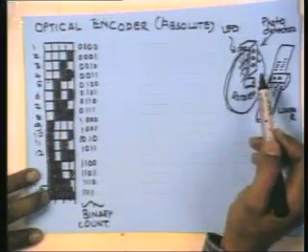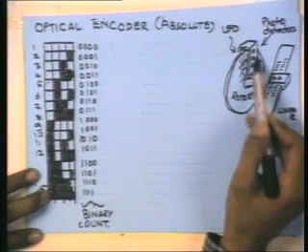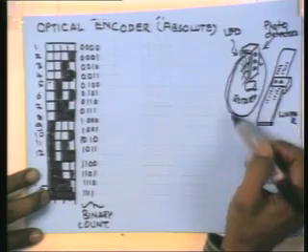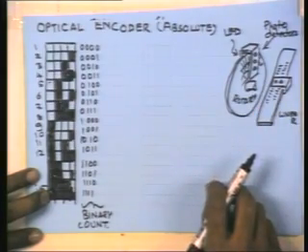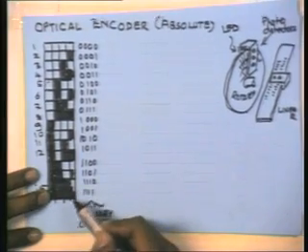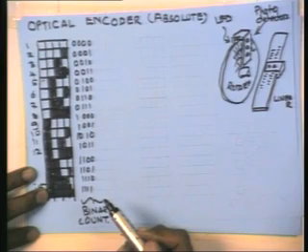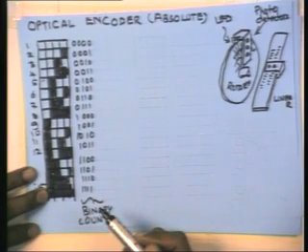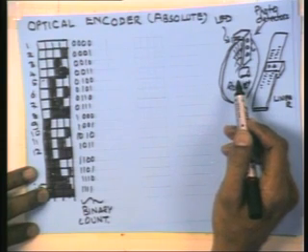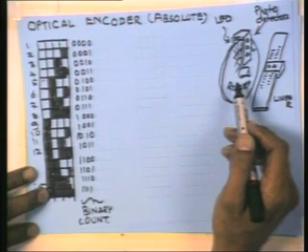Yes, you have a question? Band meaning, see, I am having patterns of zeros or ones on the encoder disk. So it depends on how many of these photodetectors I have. What I have shown here is 3 photodetectors, so this disk will be able to detect 8 different positions of the disk. But if I have 4 of them, then I have 16 such possibilities. If I have 10 of them, then I have 1024 different possibilities of the position of this rotary disk. Right?